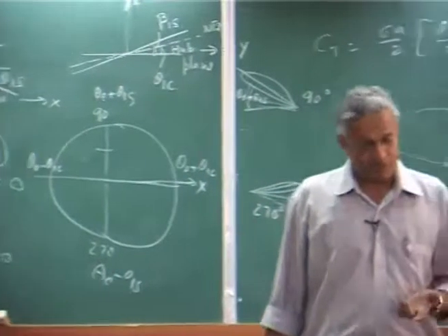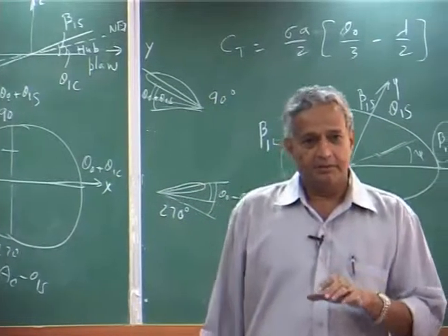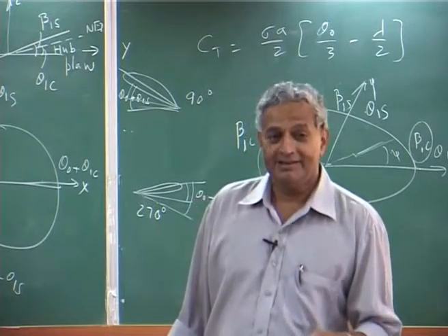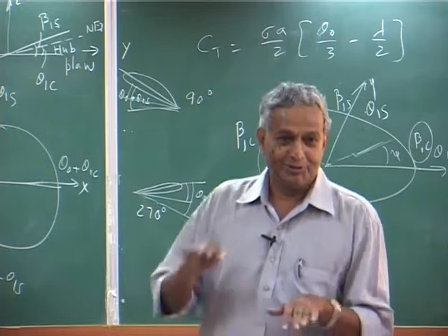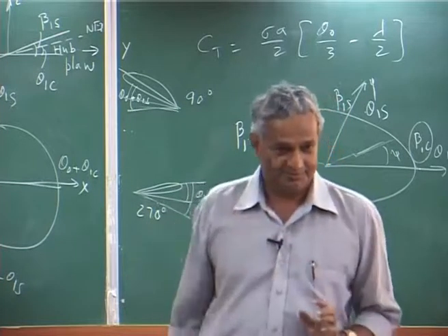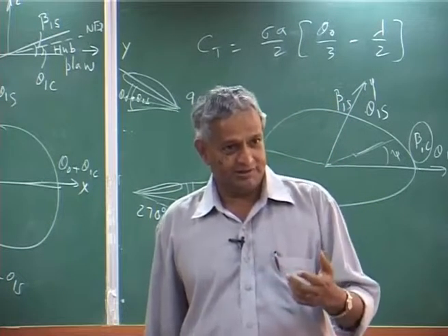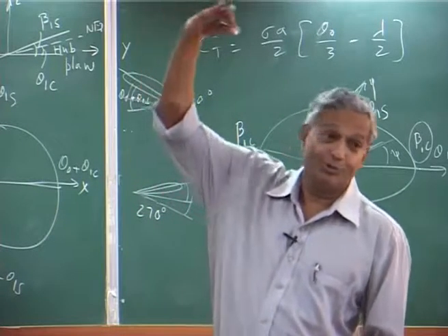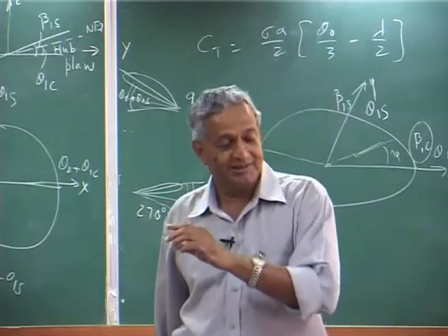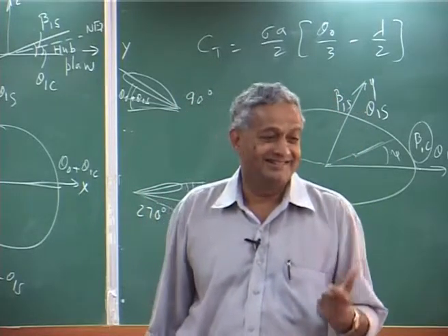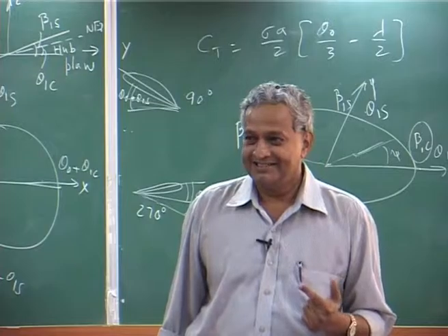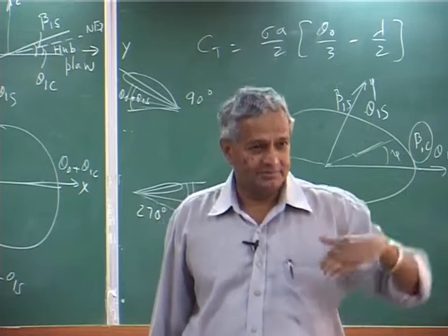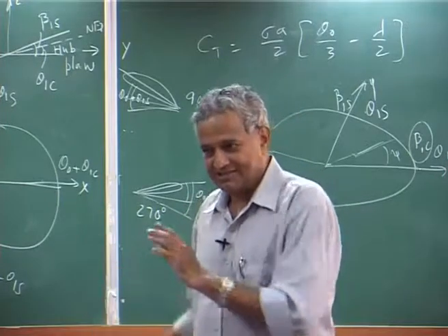Okay. Now, you can ask, what is the time lag between his input and that tilt? If there is a time lag, then you will find the pilot will give an input, but then the response may slowly come. That part we will study, because the flap is very quick. It does it within almost 1/4 of a revolution, which is substantial. We will do the time constant and the other thing.